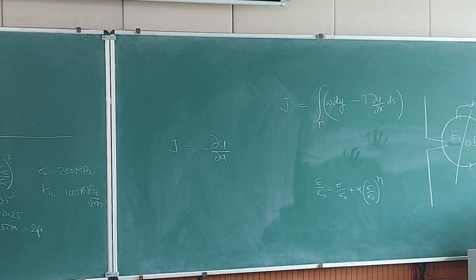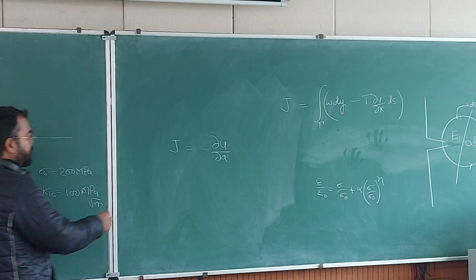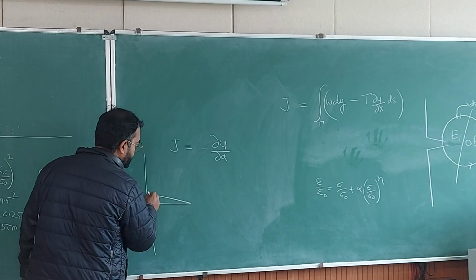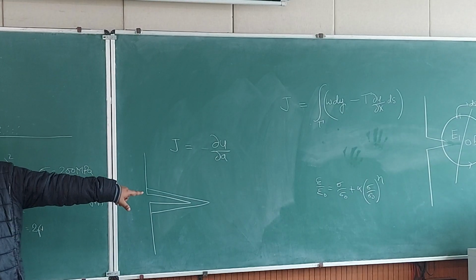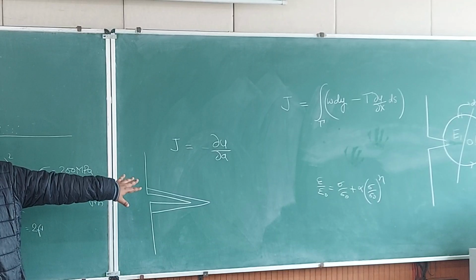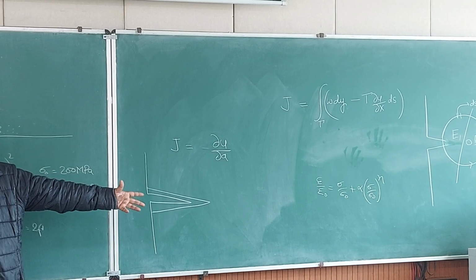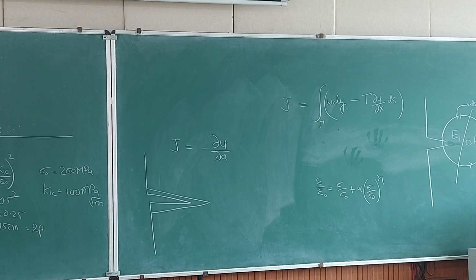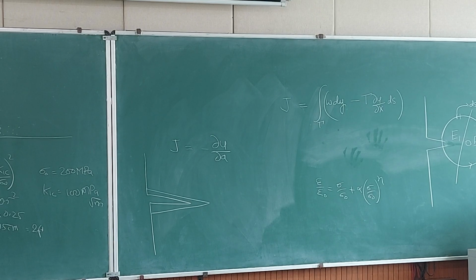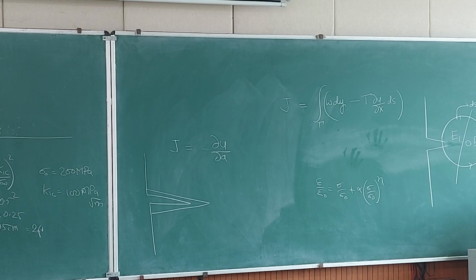Now the crack is not opening, so how can that happen? You can take this contour for two different crack lengths, and in these two different crack lengths you will have different values of J integral, because the crack tip is not the same, it's different. It is dependent on how much crack depth is there, right? We know that the stress intensity factor is going to change because of the crack depth, and constraint is going to change because of crack depth. So stress and strain conditions are going to be different on the crack. Because of that, you will have a different value of J integral for two differently deforming cracks.